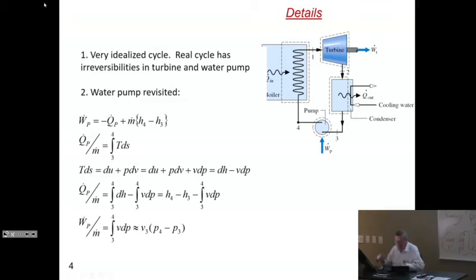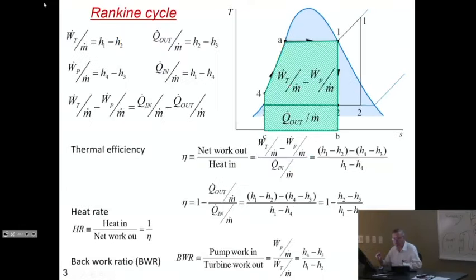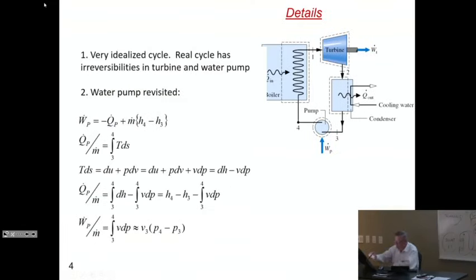And you could see that in the idealized cycle. This temperature increases a little bit. That is not due simply to irreversibilities. That is actually due to the term in the TdS that's due to dH minus VdP. That's here. Now, that means that the work, which is the integral of the VdP, is V times (P4 minus P3).